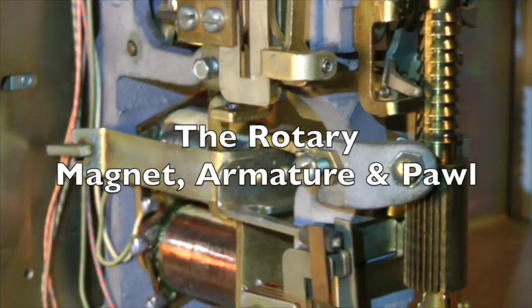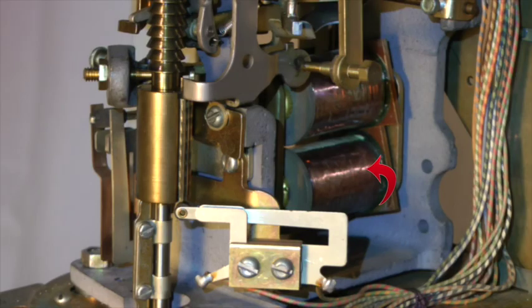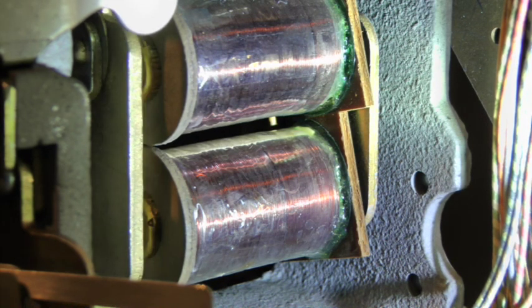Now we'll take a look at the rotary magnet. The rotary magnet is a twin coil assembly. This is the left side view of the coils. And this is the right side view. The rotary magnet is energized or magnetized each time a rotary step of the shaft is required, and it is de-energized or demagnetized after each rotary step is completed. It has an armature that is attracted to the two coils each time they are energized, and which pivots back to its released position each time the coils are de-energized.